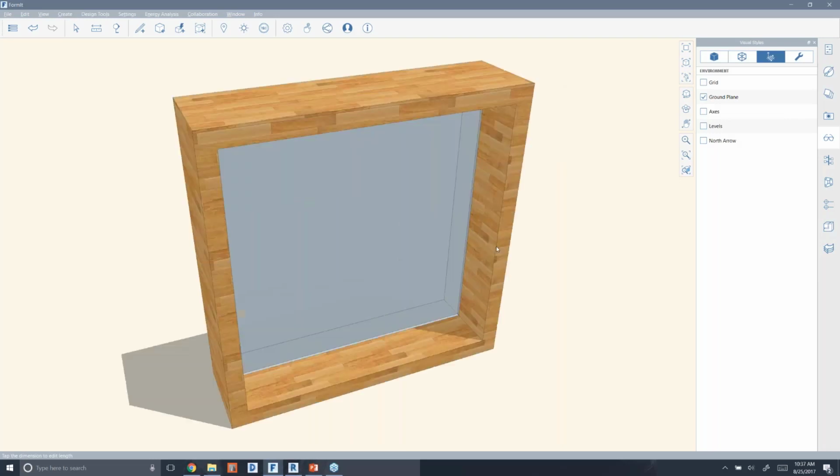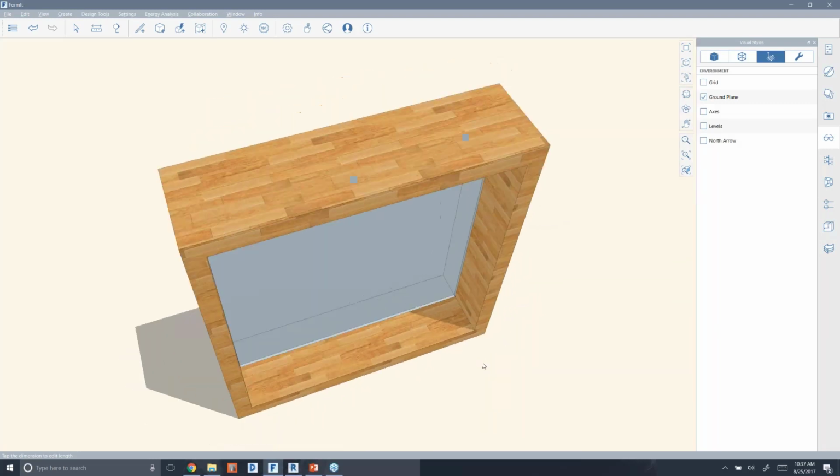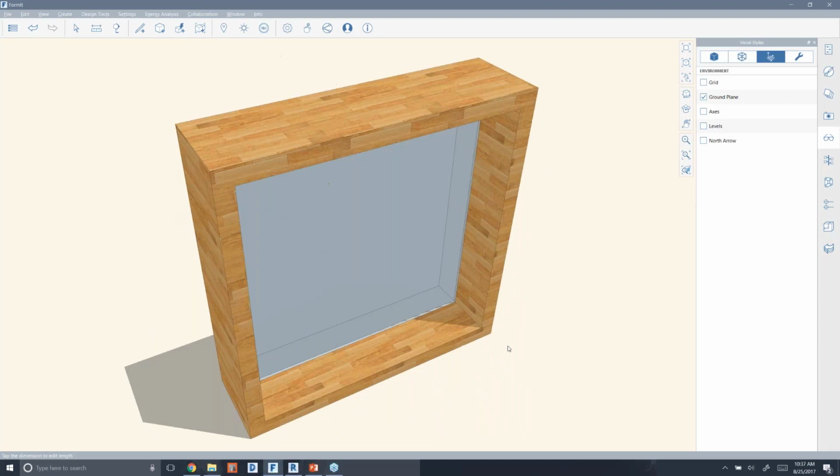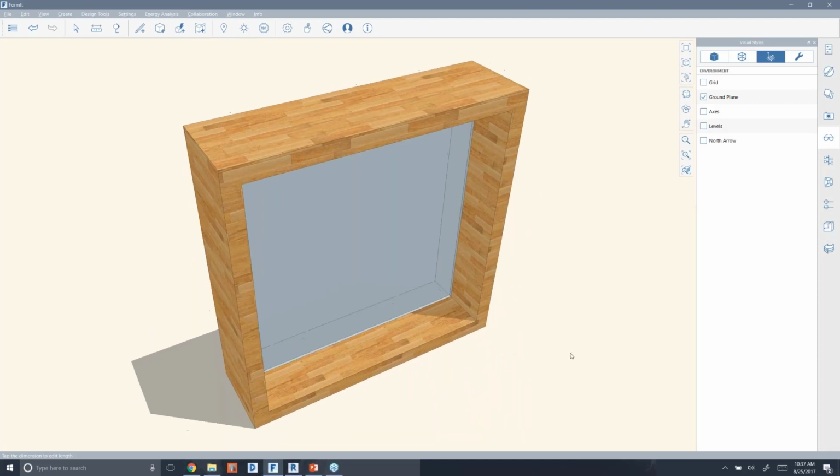So now you set up the camera angle that you're interested in. You can do a ZA and get an overall look. You can orbit around and get a different look if you want. But something like this, so you can see the object in 3 dimensions, you can see the shadow on the ground. Right around there is basically where I like to set this up. And now I'll do a quick save into the content library so we can see how the thumbnail preview looks. And we can also test what this will look like when we place it.